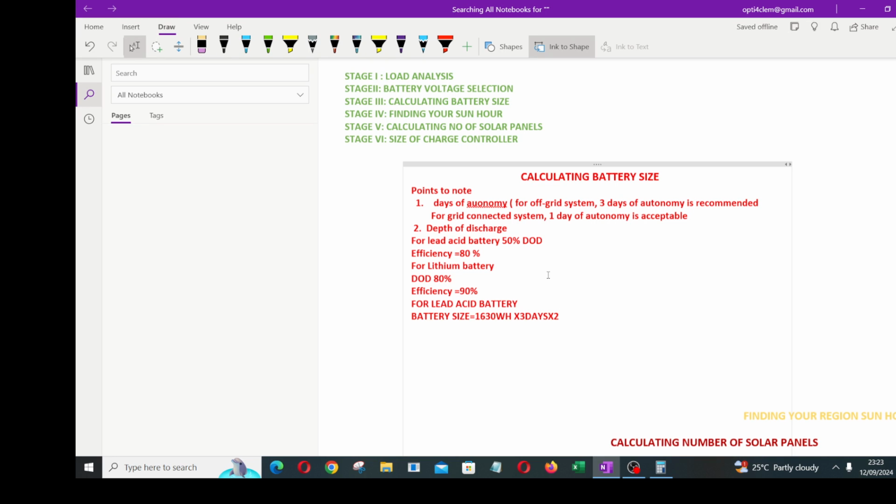You have to make provision for excess load, because when you are designing anything in electrical engineering, we always talk about diversity factors. If the total power you calculated is 1000 watt, you have to multiply that by a certain percentage. We call it diversity factor, DF, so that in case someone overloads the system by a certain amount, it shouldn't cause a problem. So 1 point multiply by 2 multiply by 1.25, that's 125%. When the system is loaded to 125%, there shouldn't be a problem.